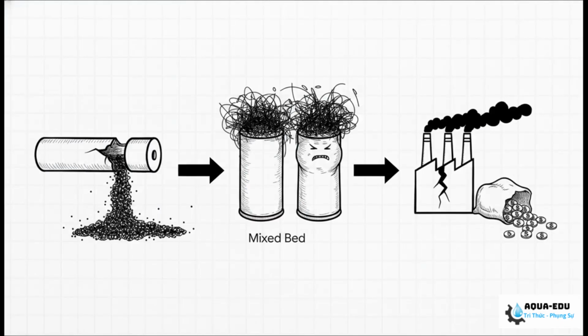If you just ignore climbing RO conductivity, that product water is going to quickly fail to meet the strict inlet standards for the mixed bed. That throws a massive ionic overload straight onto your downstream polishers. The result? The lifespan of that incredibly expensive end-stage resin is drastically reduced. Your regeneration cycles become constant, and that leads straight to severe financial losses and completely unacceptable production downtime.